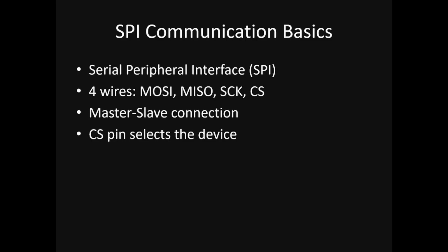The SD card module actually has 4 wires: 3 for SPI, 1 for chip select, plus power supply and ground. So our system is becoming more and more complex. That's why the circuit diagram is important, so that you can follow it and develop the same system at your end. Basically, SPI communication has wires for master output slave input, master input slave output, clock,